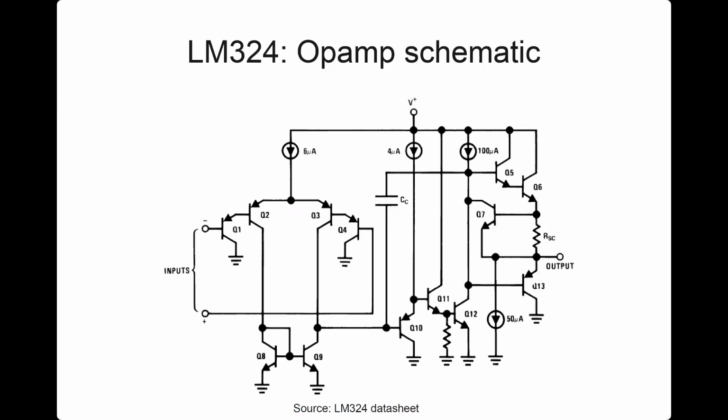I mean, does anything look recognizable after all these lectures on op amps? Okay, some symbol that's recognizable. I mean, not some symbol, some notation, right? What is it? PNP, right? Okay, they have used the equivalent of using a PMOS differential pair. There is a reason for this.